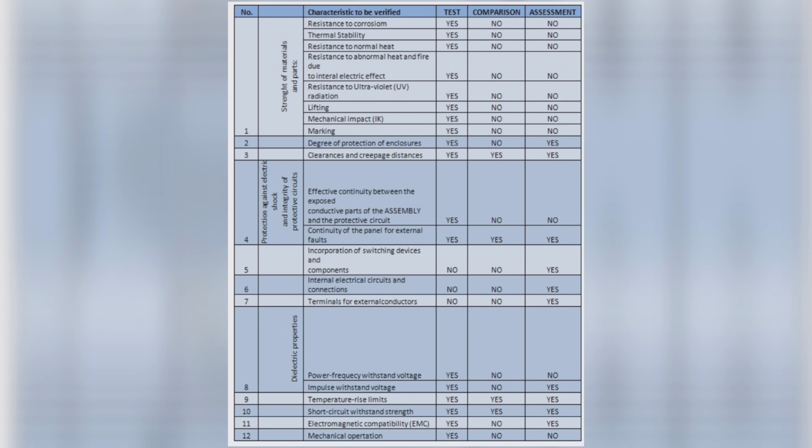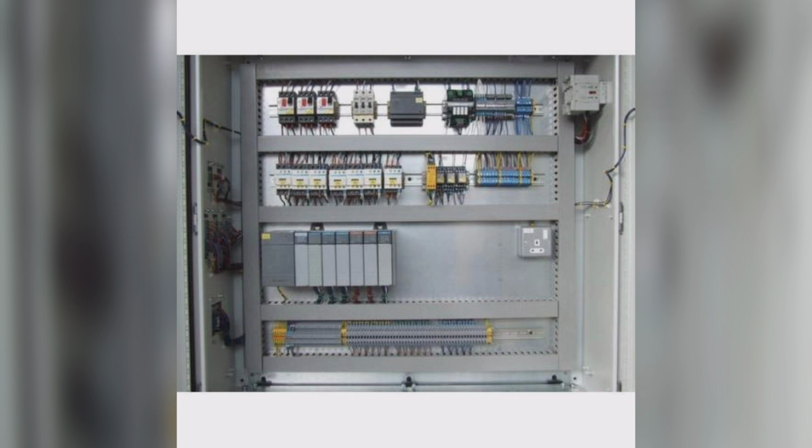There are various switchgear components used in electrical control panels. They may be electrical and mechanical also. The electrical ones include various switchgear like MCBs, contactors, MPCBs, VFDs, and all other devices, which are controlled by a remote system called a PLC, that is, a programmable logic controller. So it is called a PLC control panel when it includes PLCs.